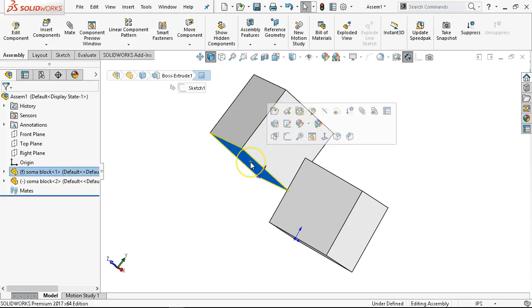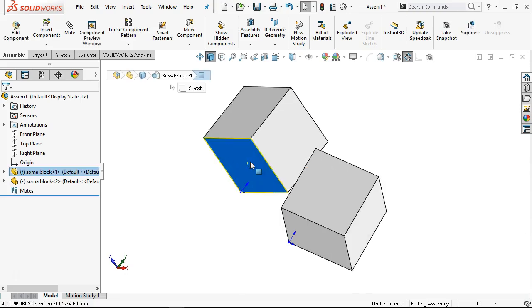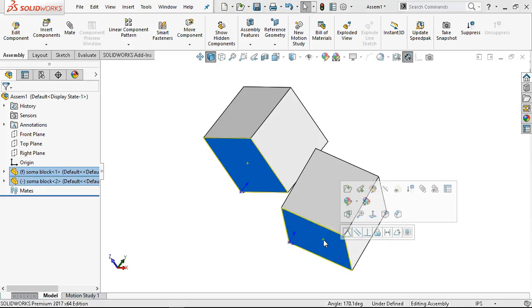Okay, so I'm big on pre-selecting, so the very first one we're going to pre-select. We have planar faces. Those are a good place to start. They make the most sense. And just like in the sketch, we're going to have coincident, parallel, perpendicular. Try not to lock. Lock's kind of one of those hokey solutions, kind of like fix in the sketches.